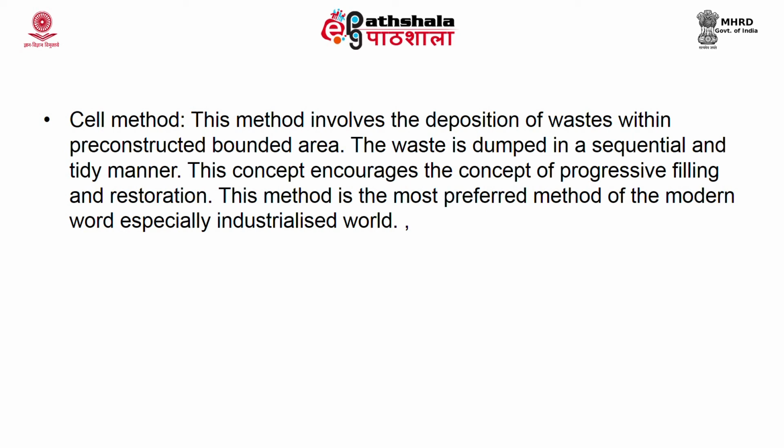The cell method will also trap much of the litter, because once you start loading in an area method, if there is wind it will carry the litter or loose materials away. When you deposit the waste by a cell method, it will trap the wind blown litter. So, that is another advantage of the cell method.